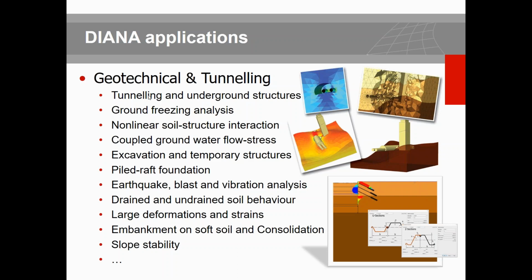So it could be NATM, TBM, or just a normal excavation. We have a ground freezing analysis based on the three-phase analysis. This is a very unique solution that we offer in conjunction with the excavation of the soft soil or sandy material zone to, say, solidify the zone of excavation.